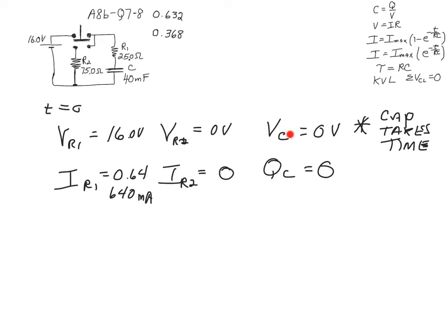So start with the capacitor. What controls the circuit is the capacitor. Capacitor takes time to charge, it takes time to discharge. That's the whole time-related concept, and that's why the time concept is controlled by both the capacitor and the resistor. So you should understand that, right? A bigger capacitor will take longer to charge. More resistance reduces the current, means it's longer to charge.